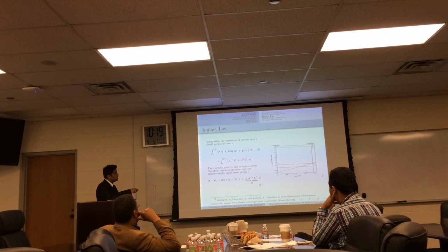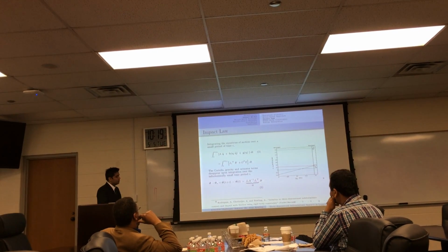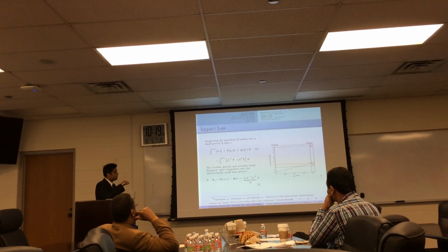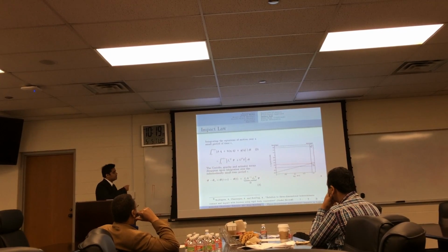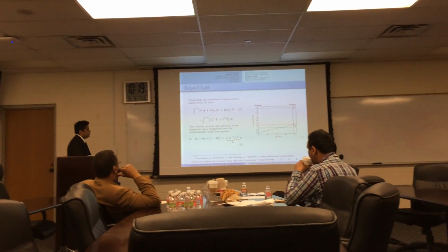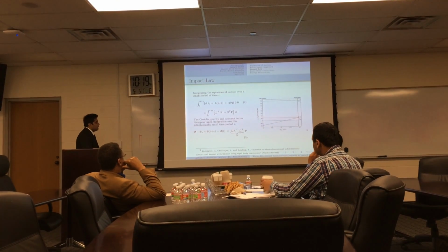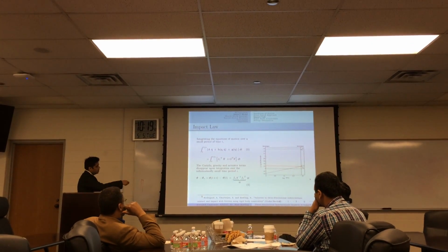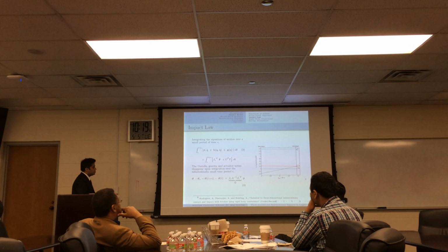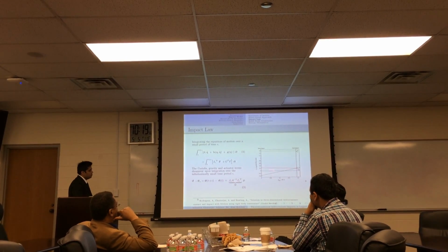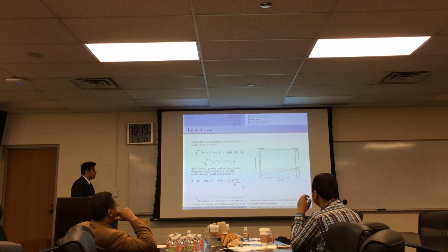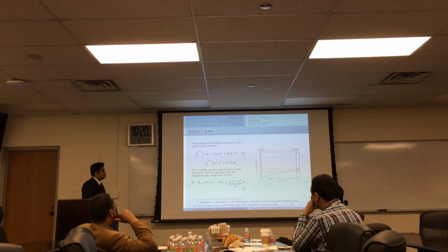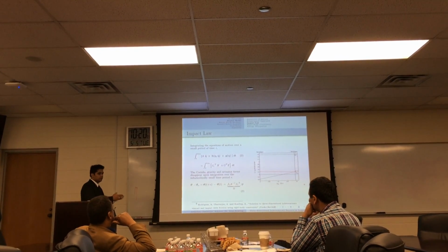But q double dot and the force are not bounded. So when we integrate that over an infinitesimally small period of time, we get a finite value, or the integration will be bounded. And we can just multiply a Jacobian matrix on both sides while inverting the inertia matrix to get the velocity and impulse relationship. So essentially what we would try to do is find this impulse that occurs over the impact event.